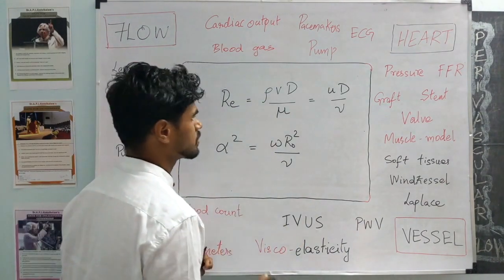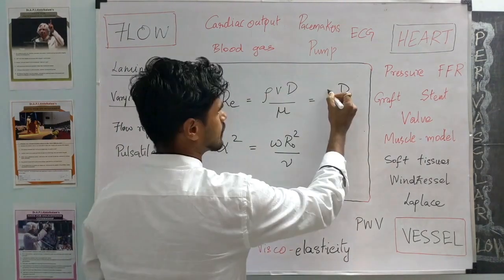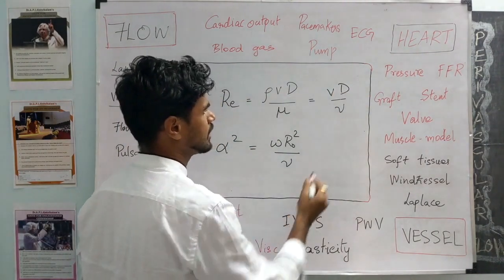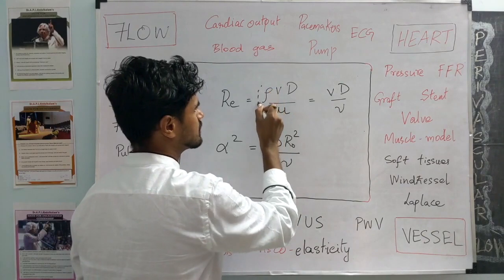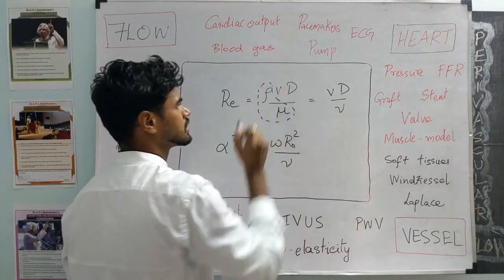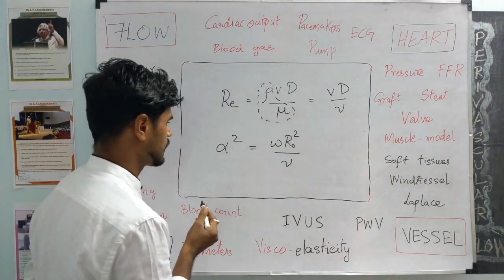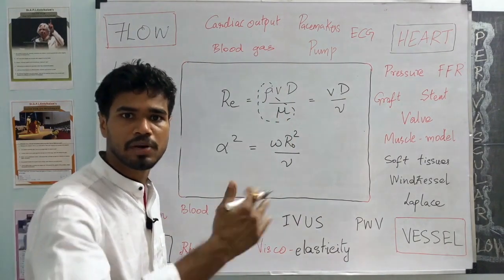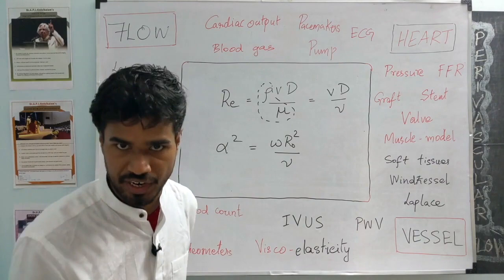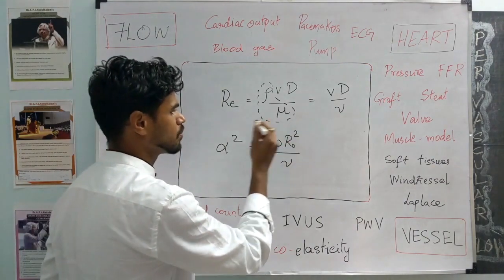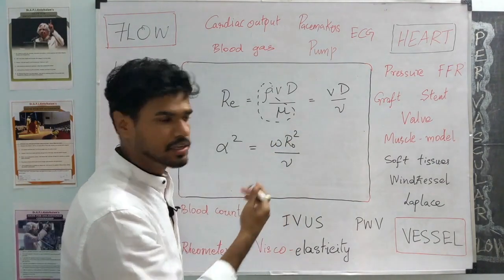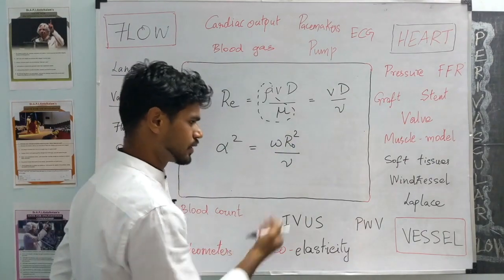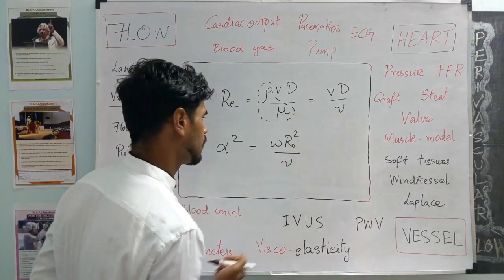The Reynolds number could also be expressed using velocity v times diameter d, and nu is the kinematic viscosity, which is nothing but this term. The alpha over here is what is known as the Womersley number. It defines whether a flow is pulsatile or more steady. Essentially it's the ratio between transient inertial forces to viscous forces, the nu we have over here.